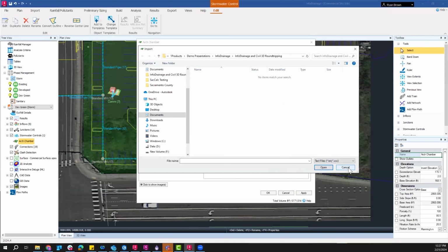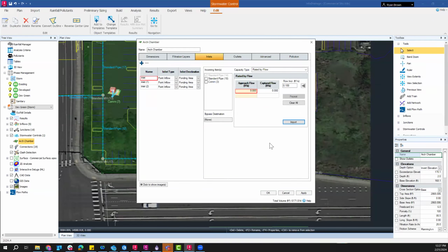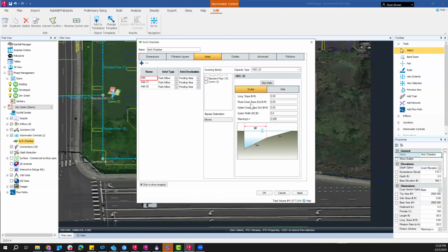So if you have a curb inlet on your street, and let's say it's on grade, is it going to show you if there is bypass on that inlet, if you maxed it and there's some small amount of bypass?